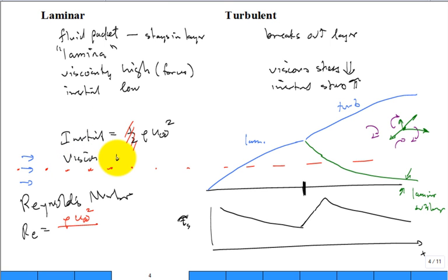Well, we think of the viscous shear stress as mu, the change in u per change in y. Well, approximate that derivative. So the viscosity, you would think, mu times u infinity minus u naught, or 0 at the surface, no slip boundary condition. And then we've got to divide by some thickness.